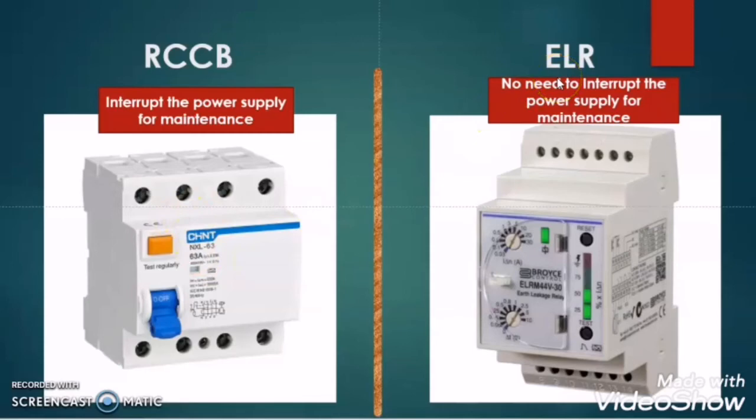But in case of ELR, it is not mandatory to interrupt the power supply in order to change the ELR or to do any maintenance in the ELR. But of course, it is recommended to cut off the power supply and then do the maintenance. But it is not mandatory in the case of ELR. In the case of RCCB, it is mandatory, it is required. We cannot avoid this.